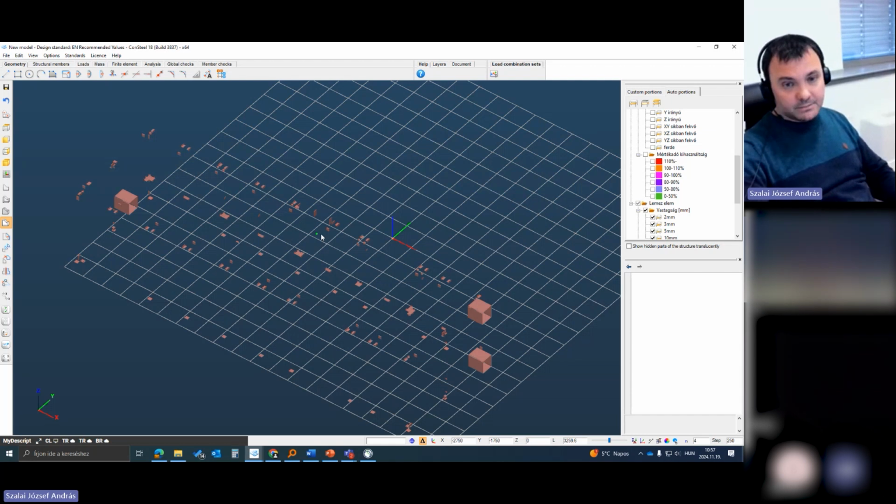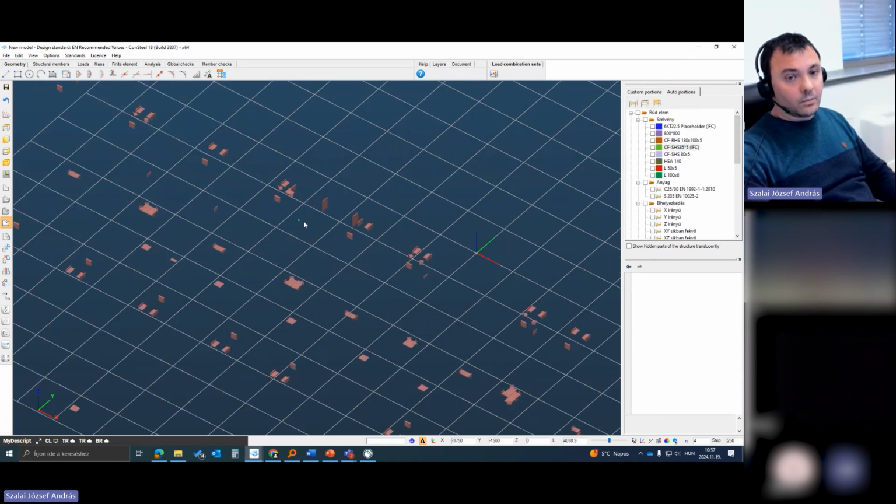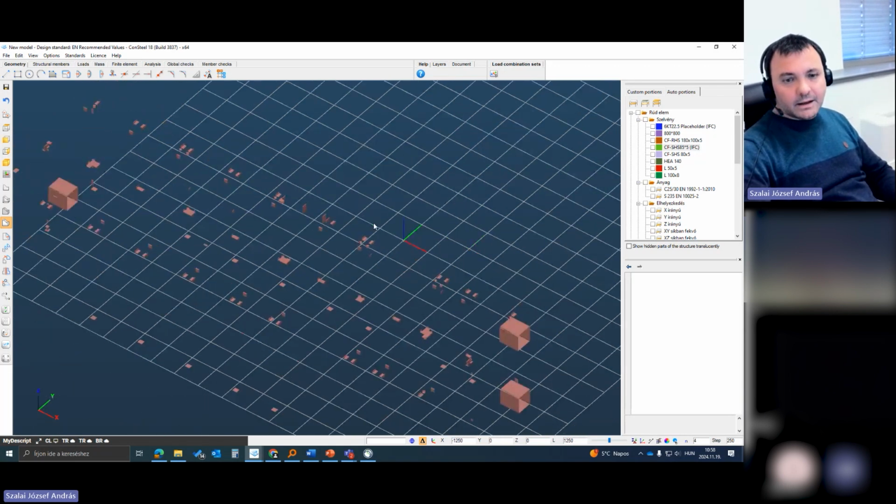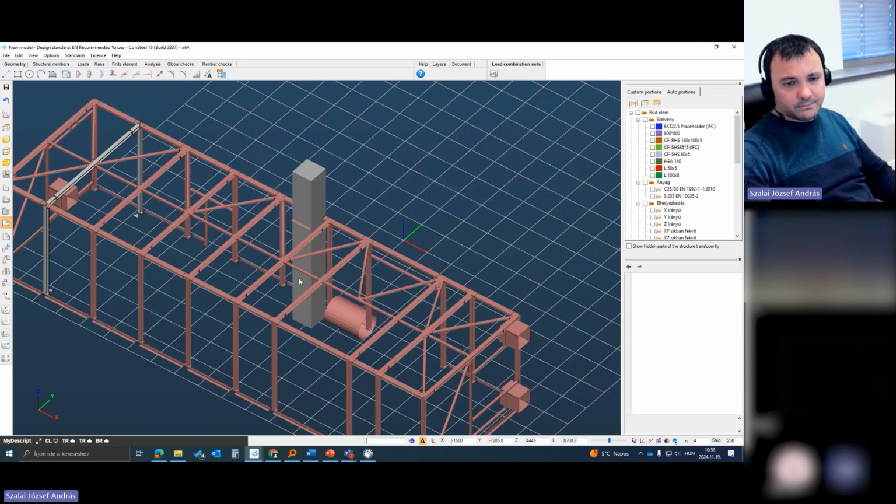And then these beams are also imported in Consteel with the parametric cross-section. So it is very important to see that these beams are part of the connection, because rather these beams are plates, just modeled as beam objects. Okay, but these are plates and part of these imported IFC models.